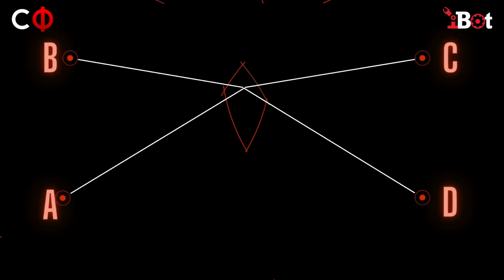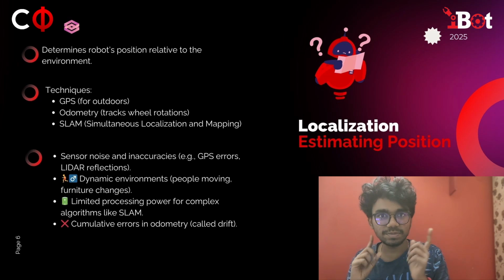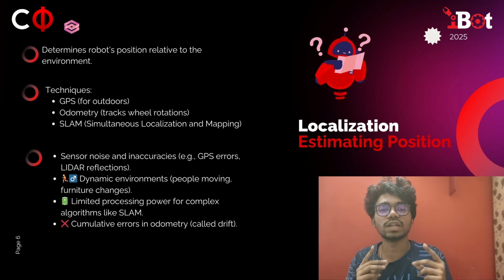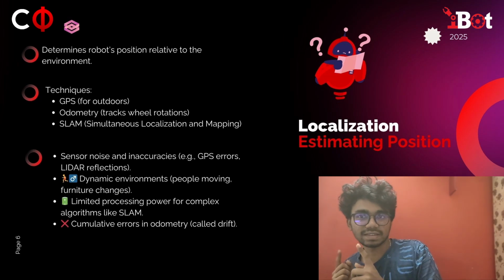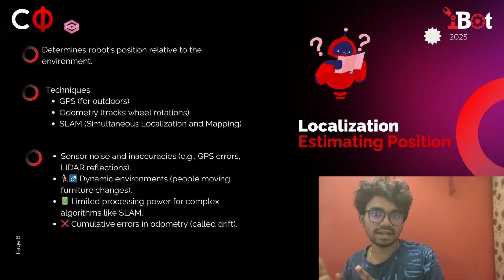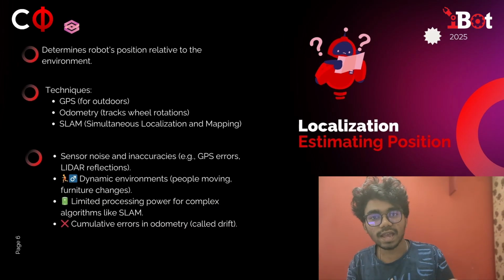Now, this is quite a big area. Let's add another sensor reading that the robot has previously calculated, and look at the intersection data again. It has decreased. As it decreased, that means we have a smaller area where the robot can be. So increasing the number of sensors technically increases the precision, and having more sensors leads to more and more accuracy.